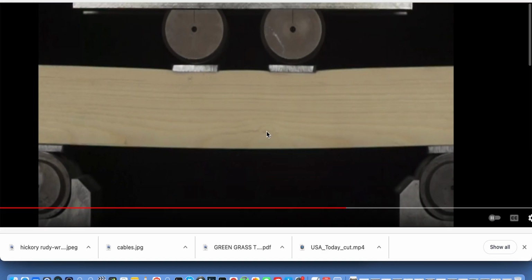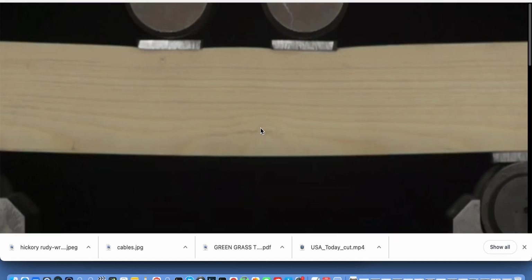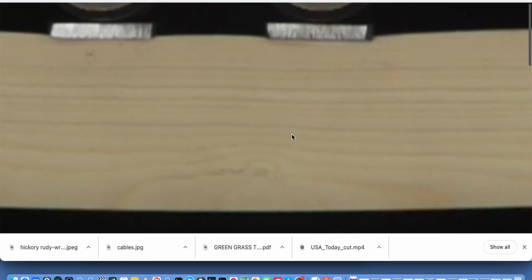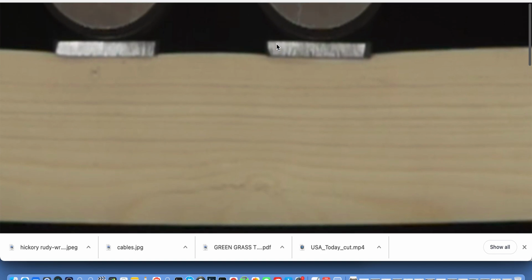So now that would be a point, and I'm just going to tag through it, and you see it break right there. There is no 45 that made it. These crossed. I already did the 45s way up here. This failed right where the inclusion is, which I won't call a defect because it's nature, but you're loading this material and expecting it to have, and it compressed too, and you see the compression in it.